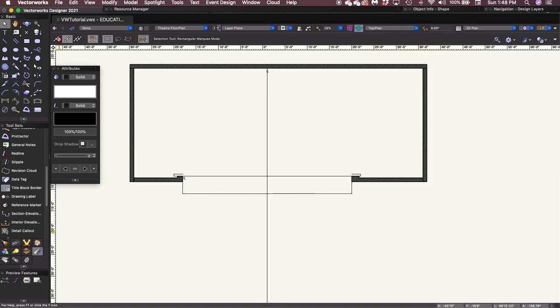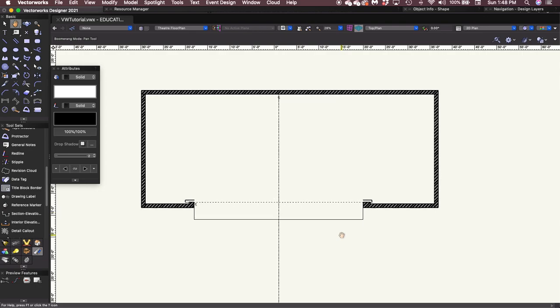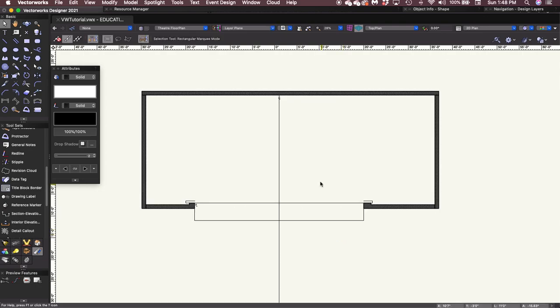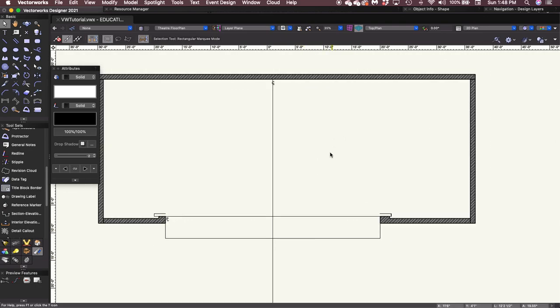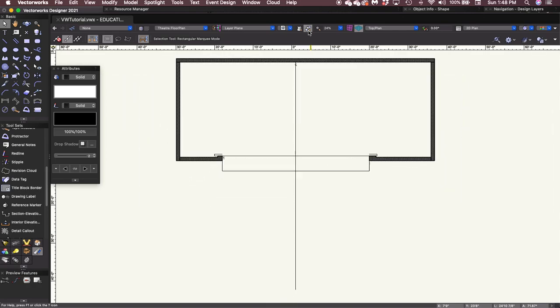And the basic structure and outline of our theater is pretty well complete. So I'm going to click on, instead of Fit to Page, I'm going to click on Fit to Objects, which is going to zoom out to everything that I have drawn on the page, so that I can see the whole thing. And I'm going to save this as a brand new file.